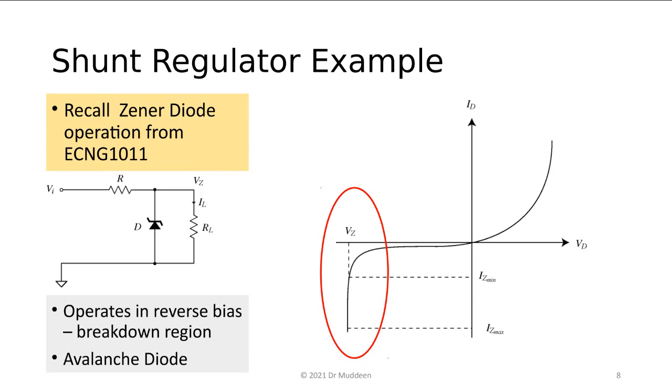And what happens is that as you increase the voltage on the cathode of the Zener, at some point in time, depending on how the Zener diode is made, the characteristic, if you watch the little diagram on the right-hand side of the screen, you keep increasing the voltage and nothing happens. And then all of a sudden at a particular value, the Zener starts to conduct, and it maintains a very constant voltage across the junctions of the Zener diode.